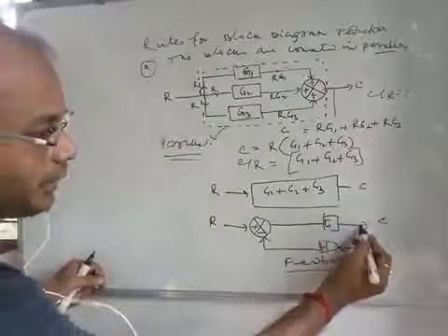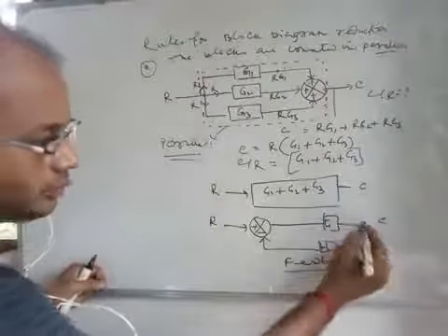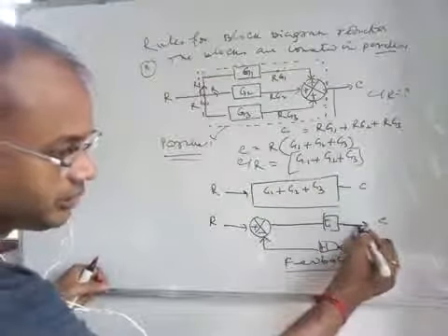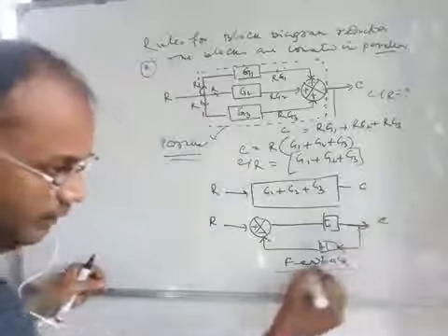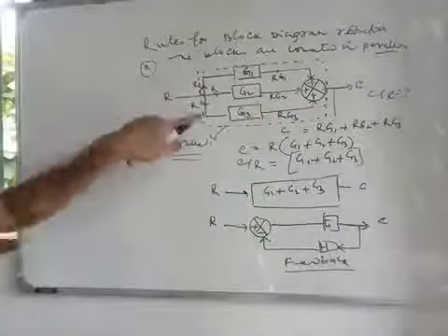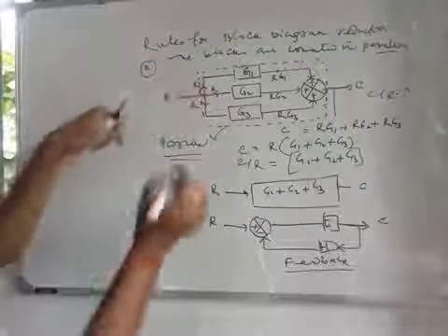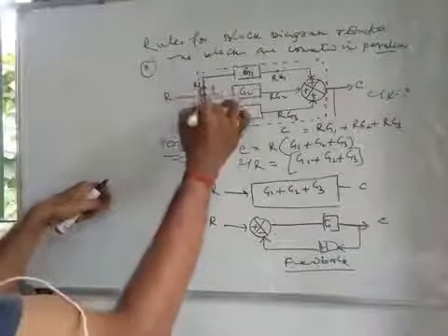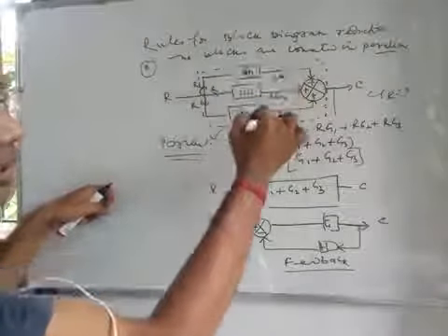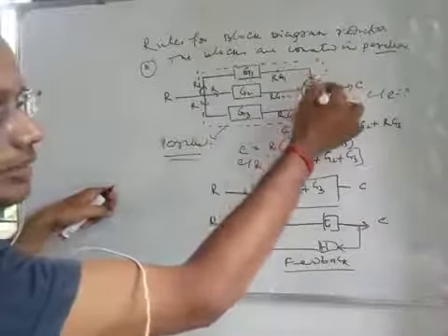They may be like this from here. So branching is not there. Actually, this is the signal. So the direction of the signal is from this to this direction, and that is coming back to the input side. This is not happening in case of parallel connections. There are different branches of signals. This is the node from where all the signals are getting branched, and then they are going through these different blocks, and finally they are summed up here.